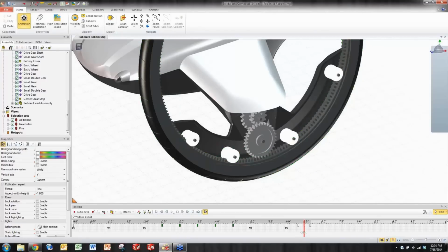So why not make these flash a couple times? I'm going to grab these 2 keys, hold down the control key on this black bar below, and copy and paste these keys behind it. And now if we watch the animation, it's not only going to flash once, it flashes twice. If I chose to, I could continue to replicate these keys and continue to have this flashing action happen.